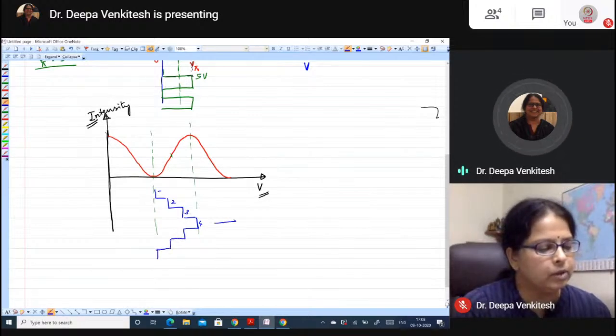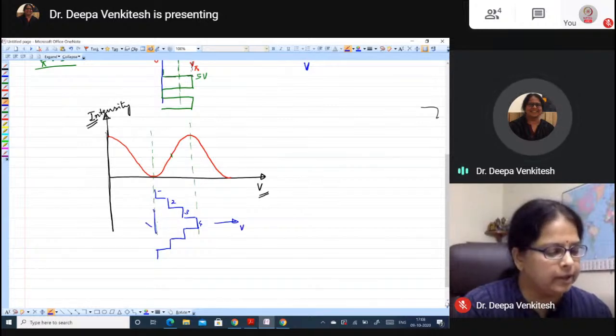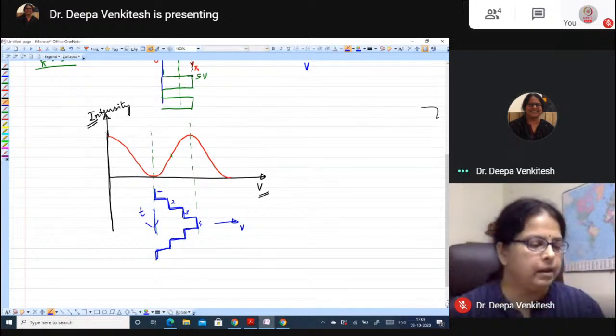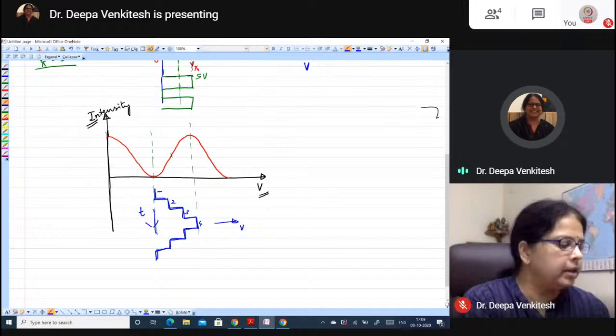This is how the PAM4 signal is looking like. So this is the voltage axis, and what I'm drawing here is actually the time axis. As time progresses, the output level goes between level 1, level 2, level 3, level 4, and let's say it is going back to this. This may represent, as we said earlier, 0, 0, 0, 1, 1, 0, 1, 1. What would be the corresponding output levels now?